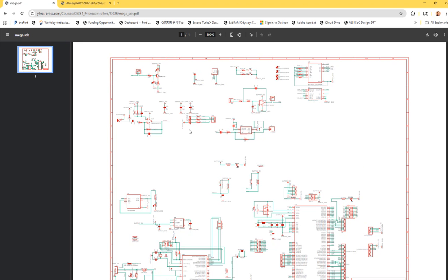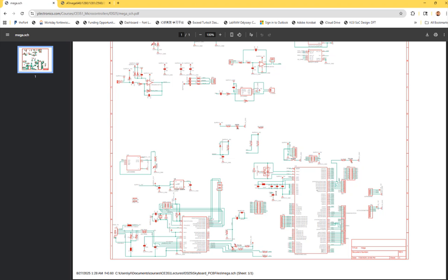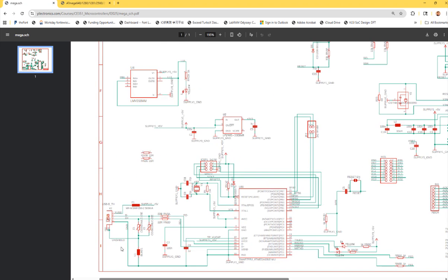So the next steps are, after we covered all these other tutorials, we know how to use ADCs and the IC cards. Those are the last 2 tutorials we are going to have. You can make a decision if you want to change or not. Okay. But you can see, grab a microcontroller schematic, the symbol, if it's available. You are not doing this by yourself. It's basically just a drag and drop. This is available in the library. If it's not, find it from somewhere else. You're not doing this by yourself. So drag and drop your schematic and figure out power supplies.